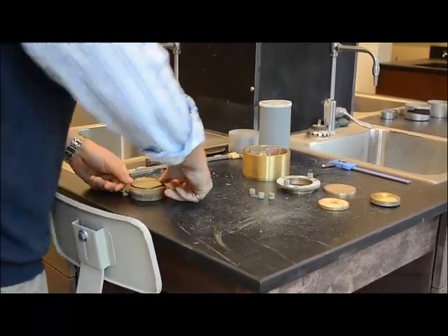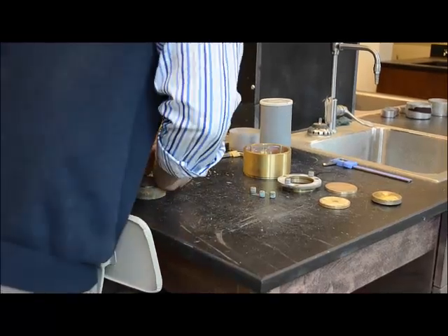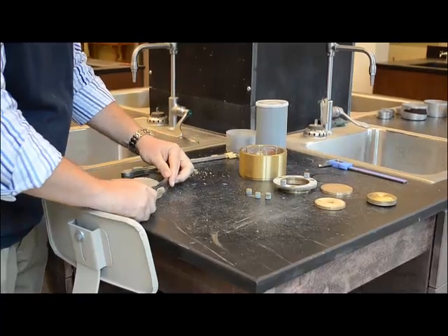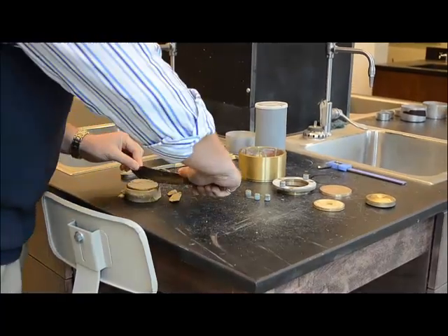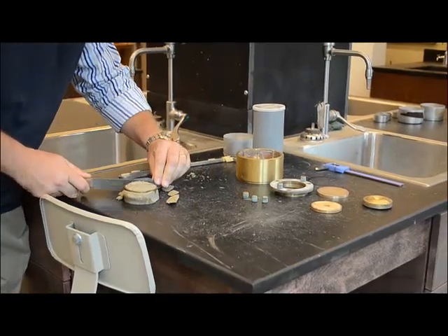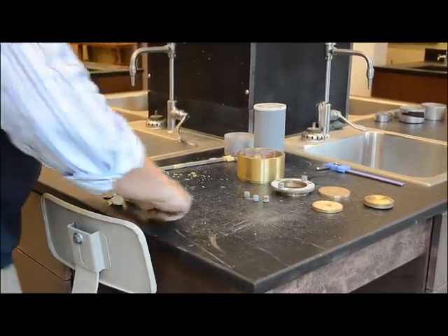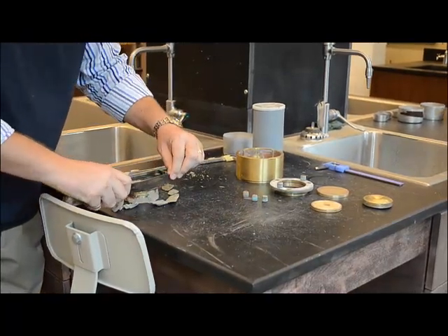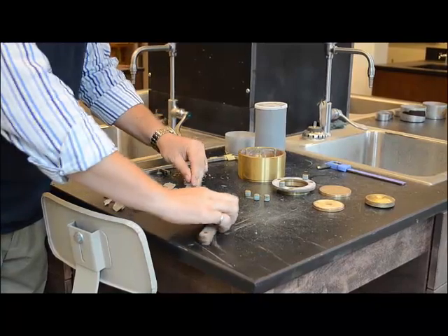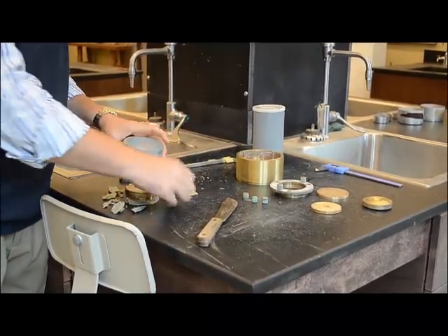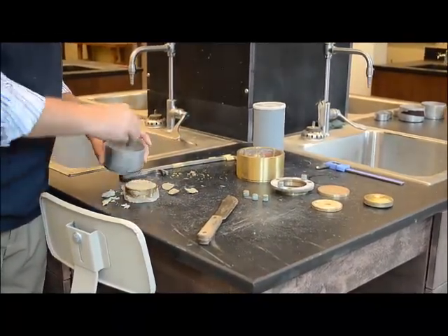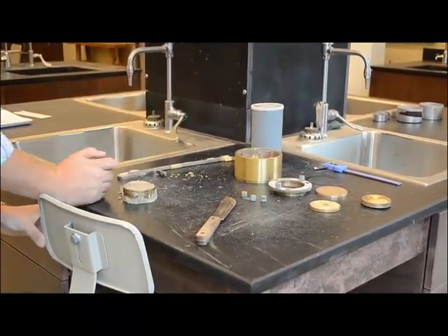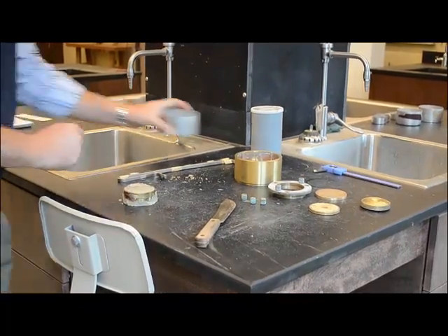Notice that the sample itself is about 2.8 or 3 inches in diameter, but the cutting ring is 2.5. That's intentional. We can take some of the excess material from the outside and collect this material to get a moisture content of the soil sample as it sits before we begin the experiment. So not only am I trimming that away from the cutting ring, but I'm going to collect some of it in a tin so we can get a wet weight, put it in the oven, and get a dry weight. We call this the before-experiment moisture content.